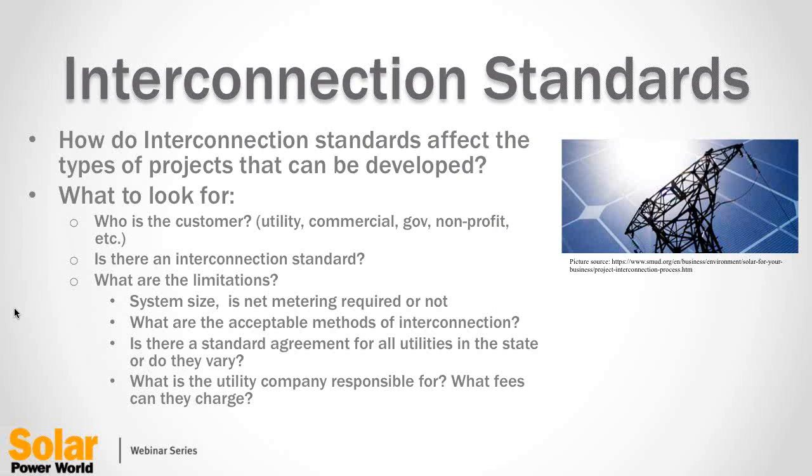A good example of that is that most inverters, if not all of them, are required to comply with UL 1741. Specifically, that standard says the inverters can't affect or control the voltage where they're feeding in power. But we're seeing more and more often, even in the Mid-Atlantic region, utilities requiring the inverters to have power factor control and active power factor control to avoid voltage flicker, frequency changes, and even voltage drop or rise on the distribution lines. So it's really important to know who your customer is.